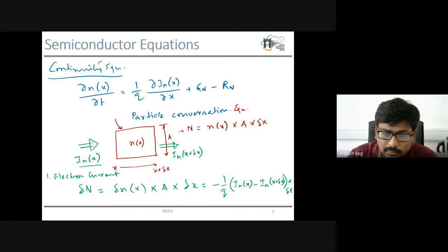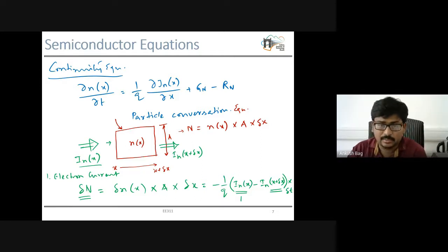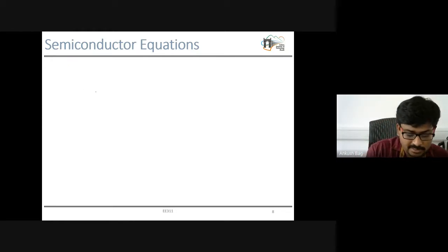If we divide the current using q and multiply by t, then you get the total change in the electron concentration, del N, which is due to the difference in the current going into this terminal and going out from the other terminal. Due to this there will be variation in the total electron concentration del N. So this is the equation, and now we can further simplify this.